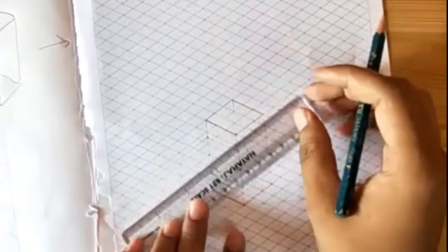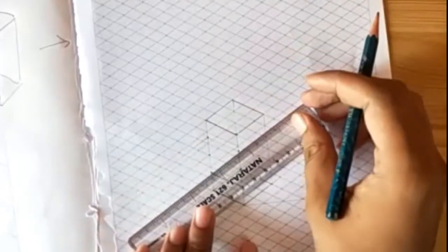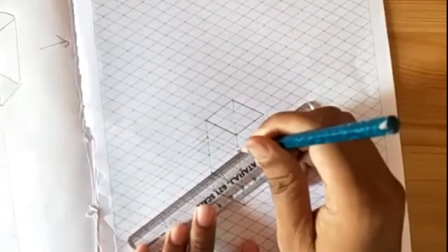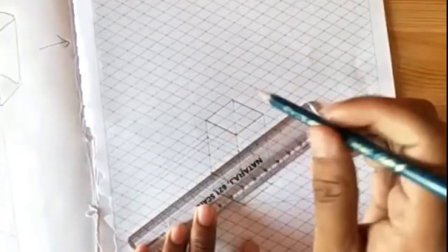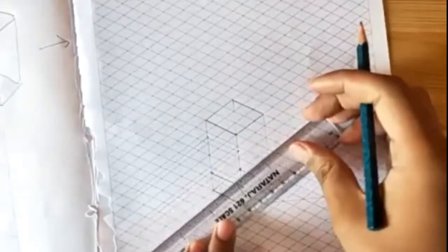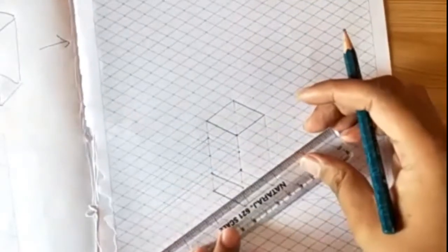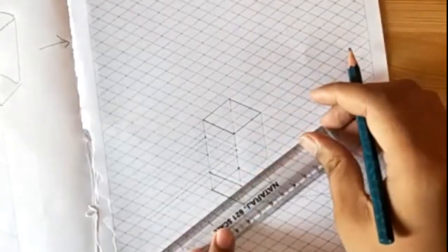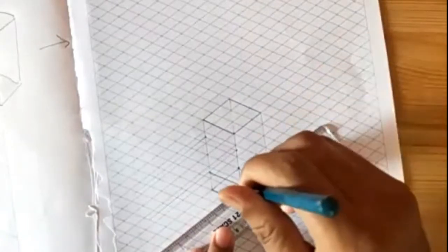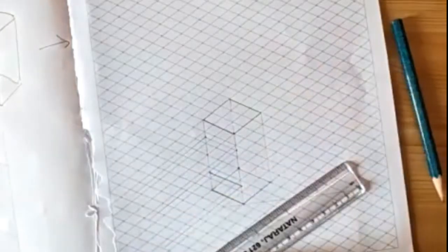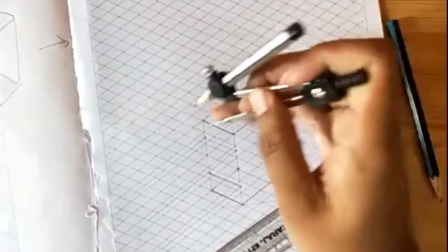Again later, after that, from the point number 2, you can see here, if this is the point number 2, the point number 2 and the point number 4 coincide. You just drop a line. Fine. Again from the point number 3. This is your point number 3. The third corner of your square. Again from this point you drop a line. So what is the length of the total projection? The length of the total projection is 6 boxes. Measure 6 boxes.